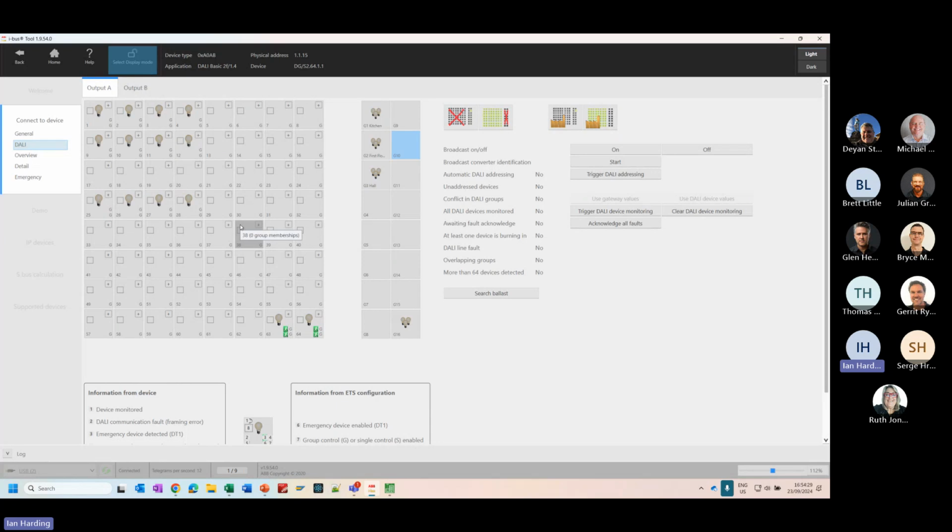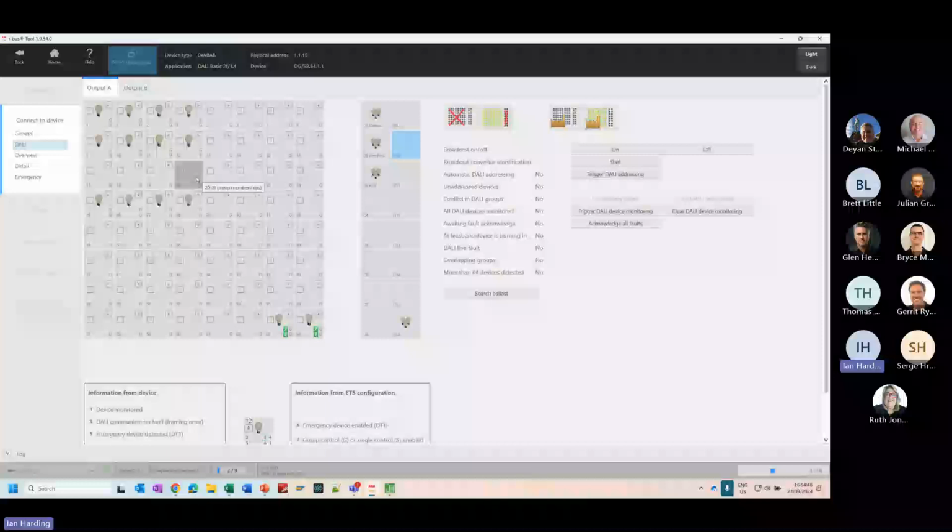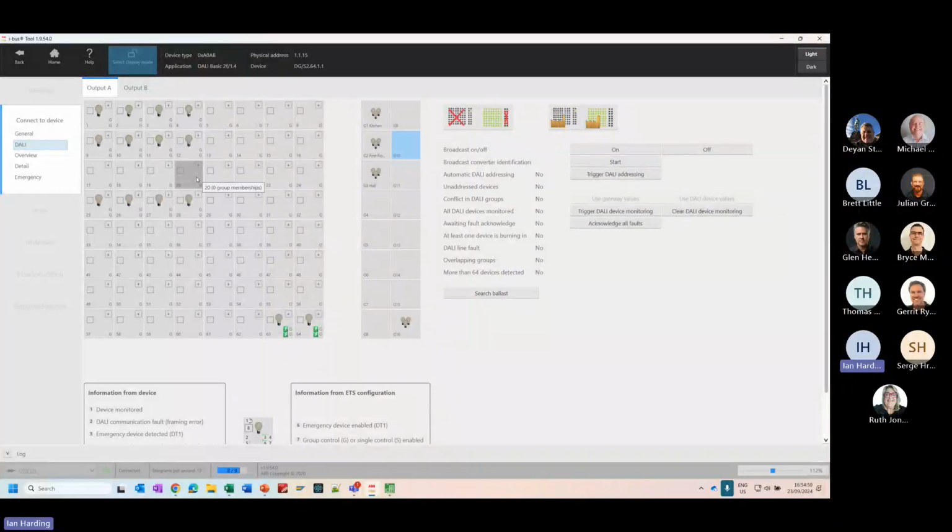I don't have to do anything else. It's done straight away. I don't have to connect to a DALI line. I have nothing else to do. So that's the simplicity of this: we can drag and drop wherever we want, and we can create all the groups. You walk into an office space, and when DALI has randomly addressed all the devices at initial startup, I can drag and drop them all so they make sense afterwards. And once I update my documentation, everything will be clear.